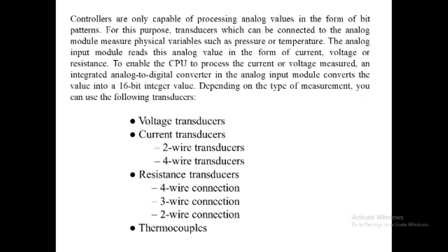The resolution of an analog module depends on the converter and its external circuitry. As an approximation of the analog signal to be acquired, the output is returned as a step curve, and the resolution determines the number of increments of an analog value along this step curve.